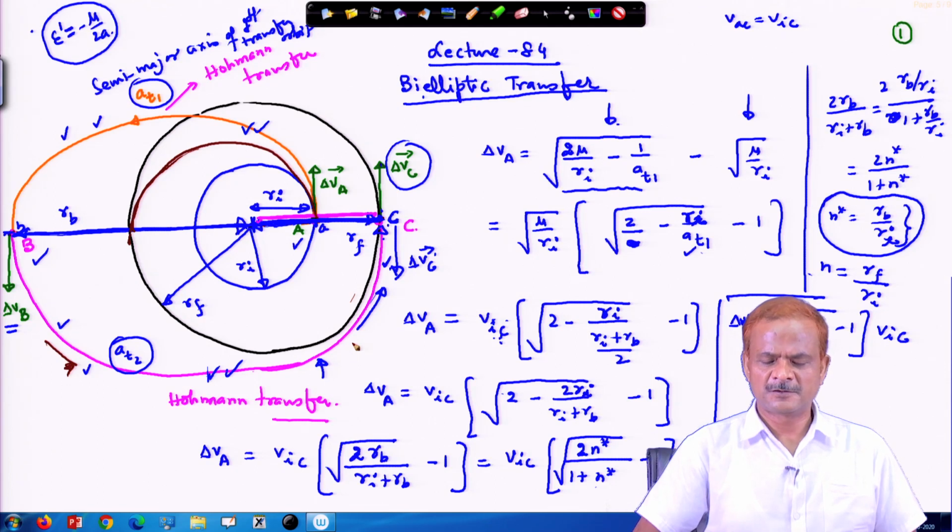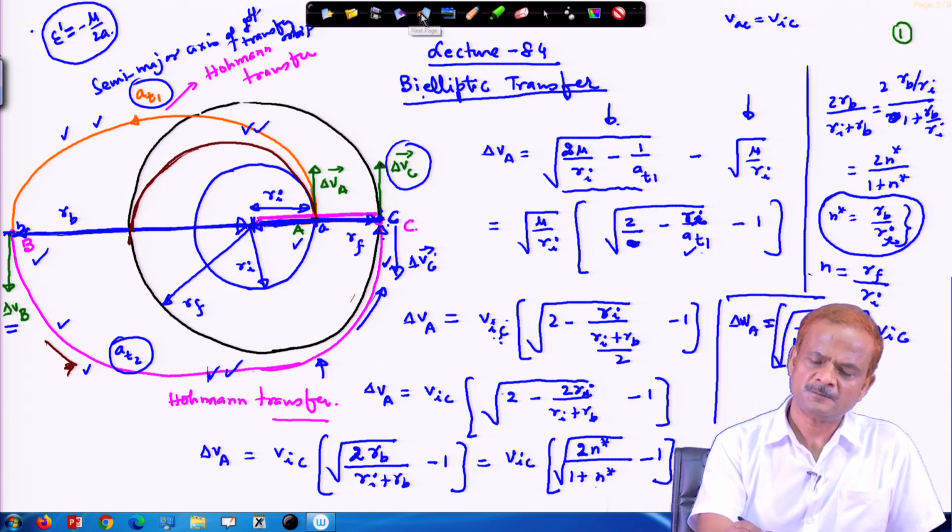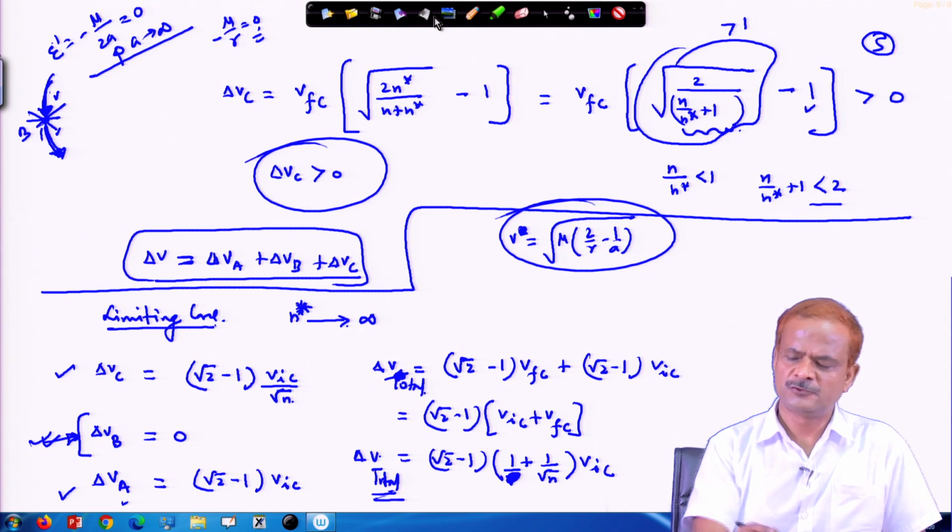The shortest will be a straight line going from one point to another point with infinite velocity, but this is not practical, you cannot get infinite velocity. And therefore, the shortest possible time you always get in the hyperbolic orbit. Next it goes in the parabolic orbit and then the elliptic orbit. So, accordingly we choose our orbit, and automatically you will be forced to use that kind of configuration.